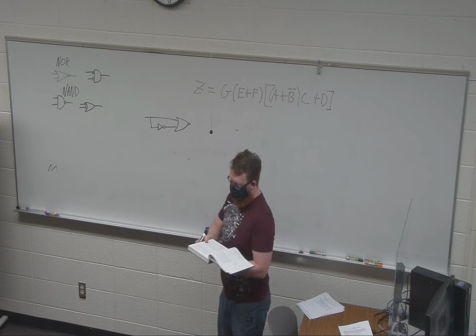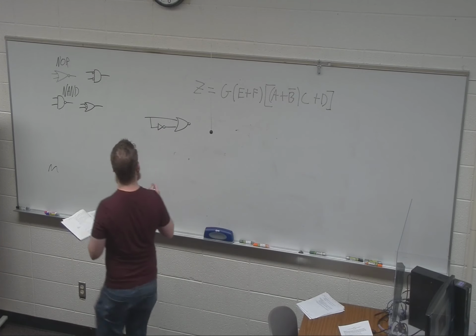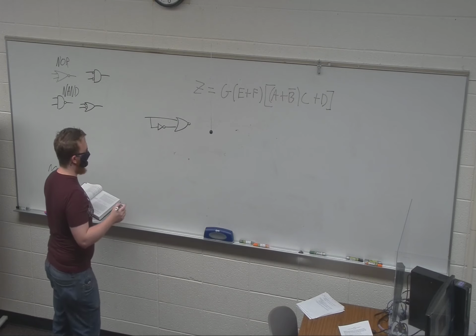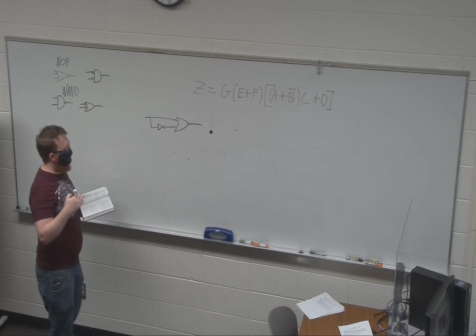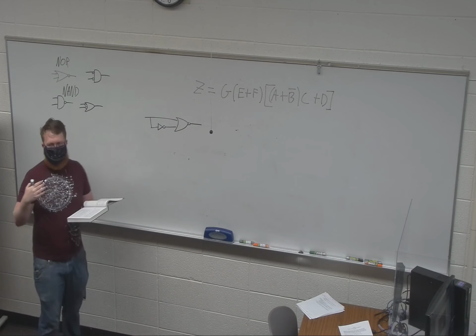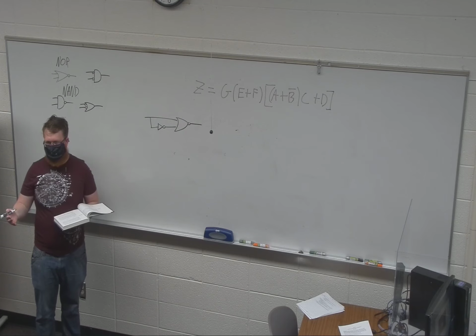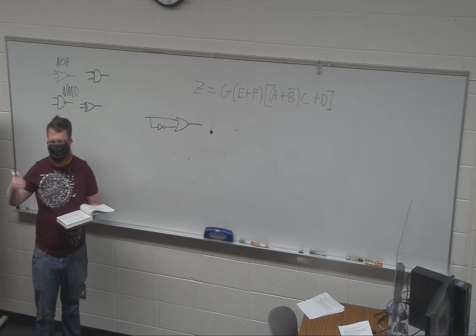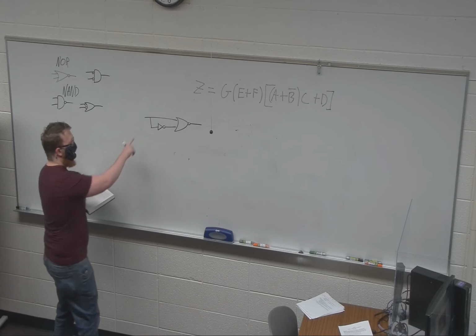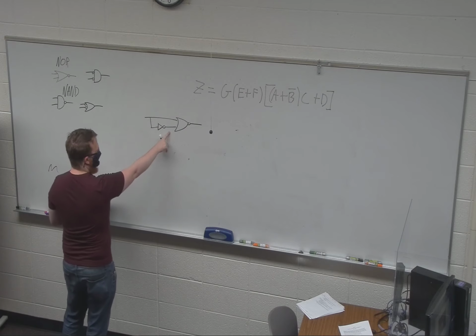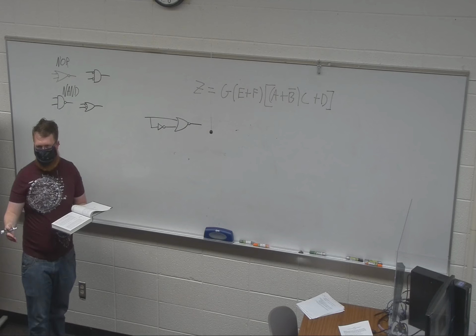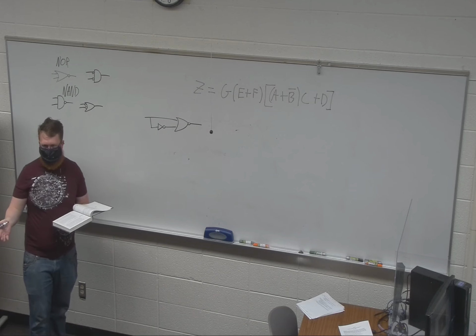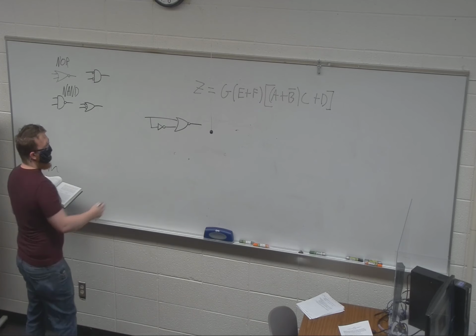And this is going to end up with what we call a static 1 hazard. And these happen because these devices are real devices, right? They're not instantaneously changing. If I put the value here and it changes, there's going to be some sort of delay. And later we'll define this as propagation delay. That's what you're going to run into.